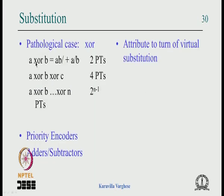So if you have A XOR B, then you will end up with AB bar or A bar B, 2 product terms. But if you have A XOR B XOR C, you can expand that, and it will become 4 product terms. I have shown up to n, I should have given some indexes, definitely A to n is not n. But I hope you understand that if there are n XOR inputs, from 1 to n, then you have 2 raised to n minus 1 product terms.